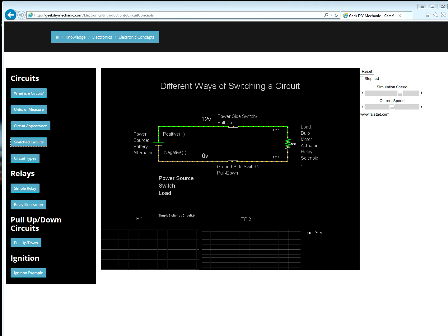The next switch will teach another important concept that you will constantly draw upon when working on automotive circuits. Here it is. Voltage drop only occurs across a load when current is flowing. Again, so important. Voltage drop only occurs across the load when current is flowing. Let's see this in action by closing the pull-up switch. It is closed. And opening the pull down, this bottom switch.